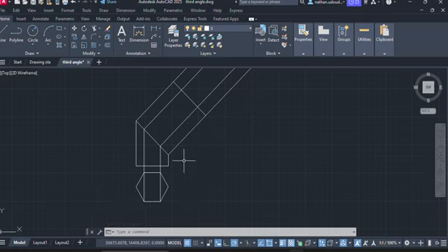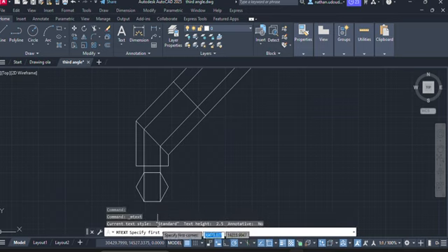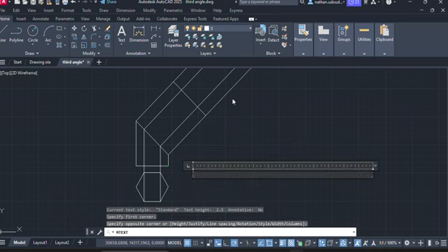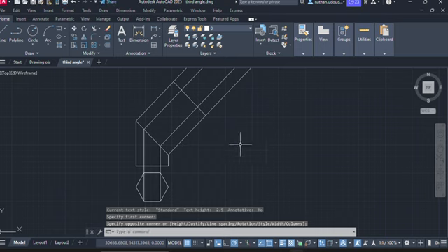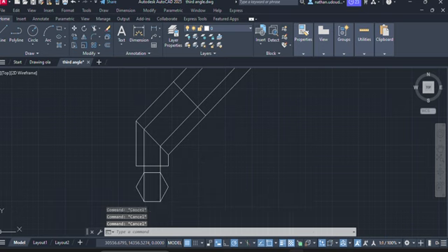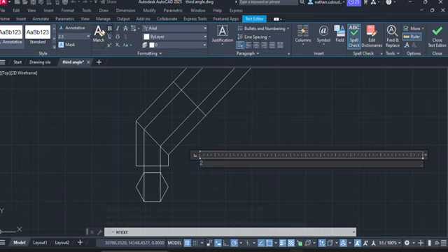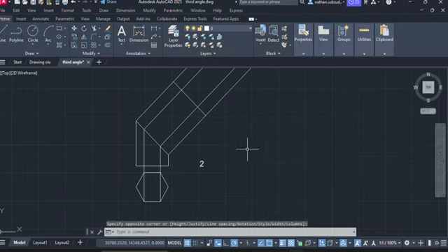So you come to your text. So this is your text, multi-line text, and then you pick up, let's pick up, so now let's take number 2, Control A. So let's increase the text. Let's increase it to around 10. Enter. Okay, then close the editor. So now move or copy. CO, enter.